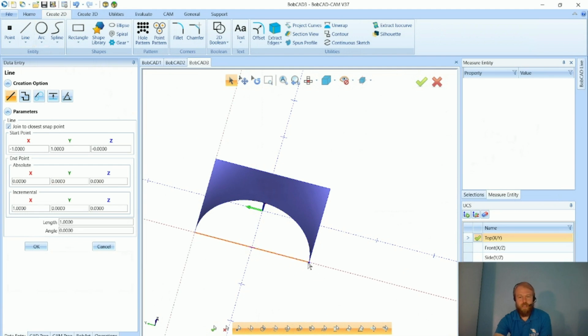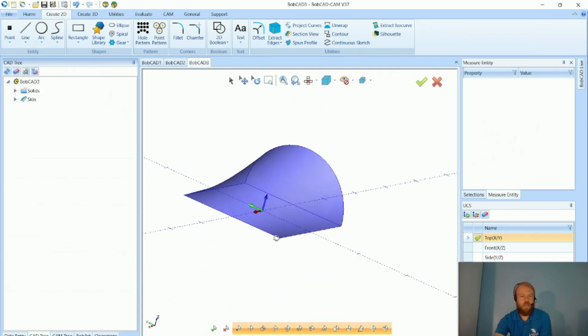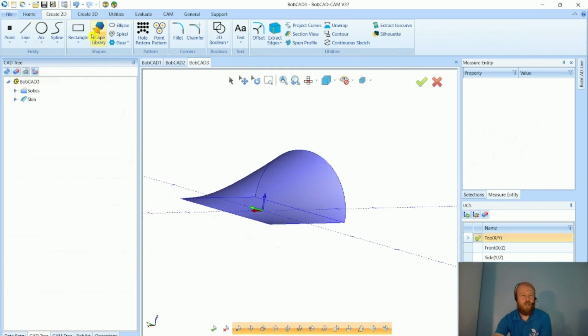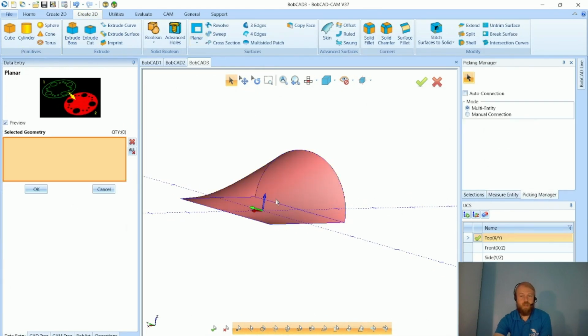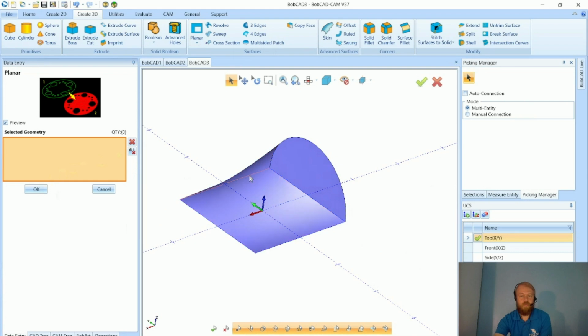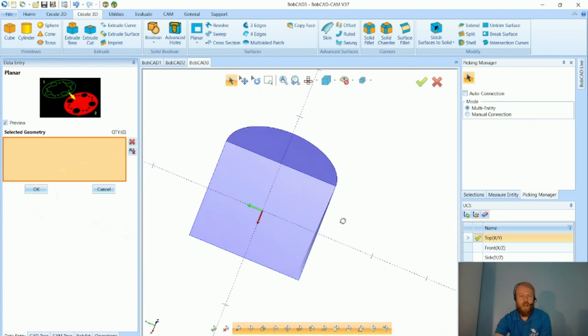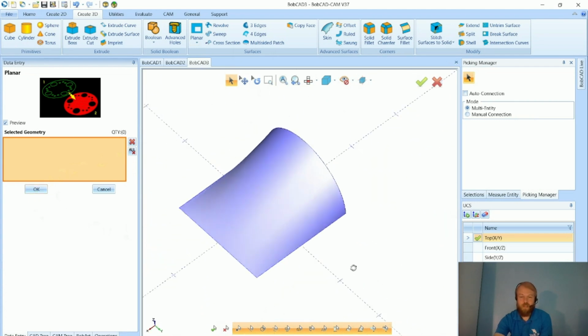And now if I wanted to, maybe I could create the line that I deleted. I can recreate it right here, point to point here. I could go into my Create 3D and Planar Surface, click on these two edges right here, cap that, go down to the bottom, create a planar surface with the square here to cap that side. And now I've almost got a solid.